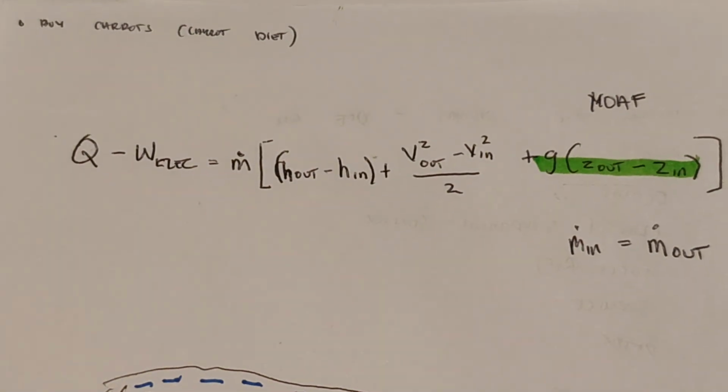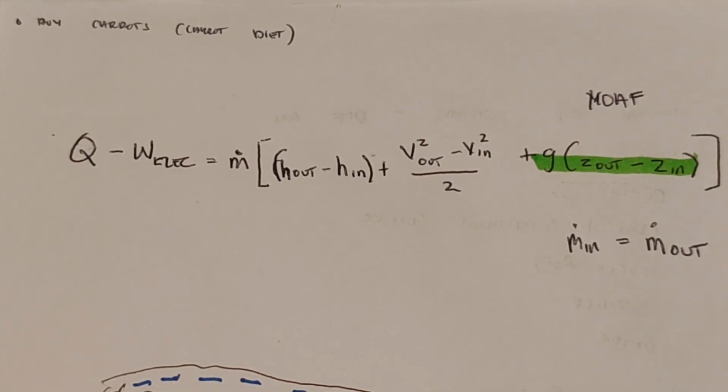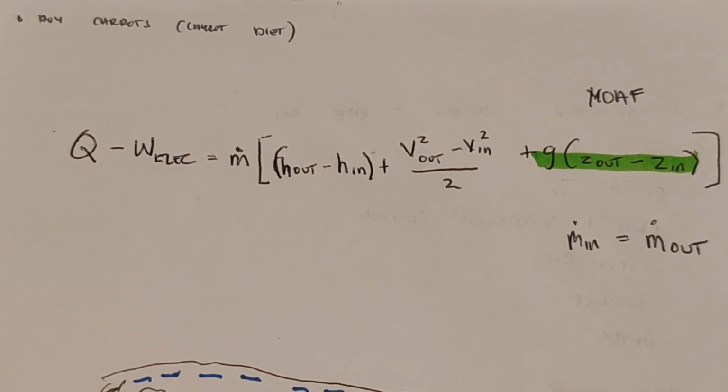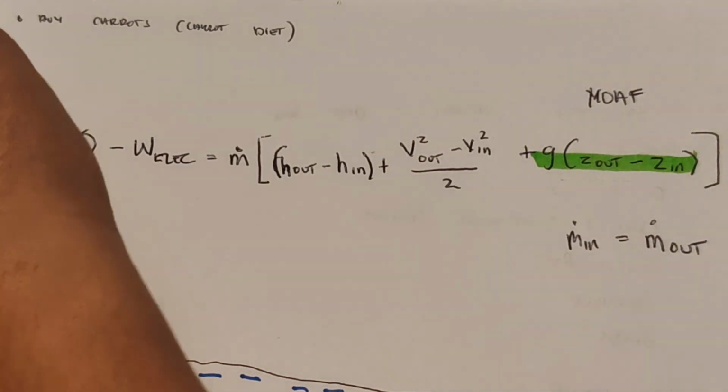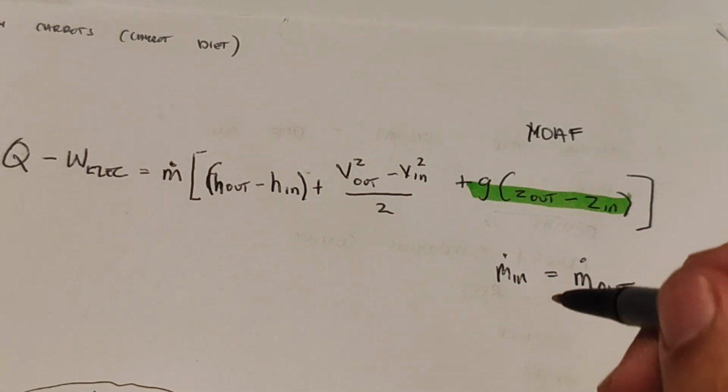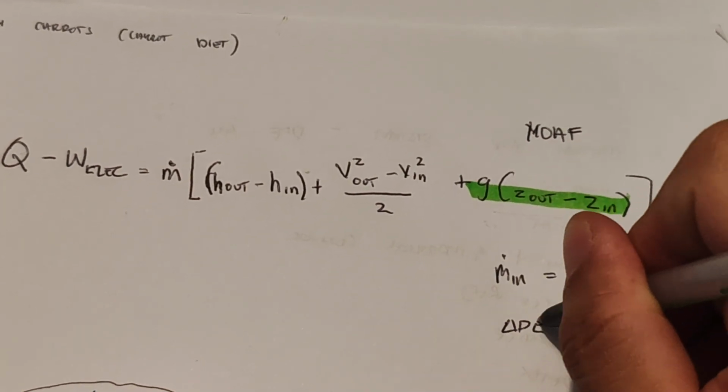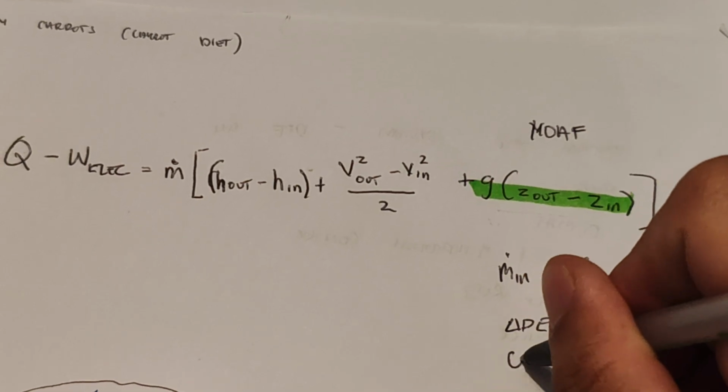Heat loss. As we talked before, we consider that the casing is adiabatic since we are not measuring its temperature. Is it perfectly adiabatic in real life? No. The plastic gets warm, but the air moves so fast it doesn't have time to lose significant heat to the wall. So we set our Q as 0. So let's write PE is equal to 0. Q is equal to 0. So we're gonna cancel that out now.